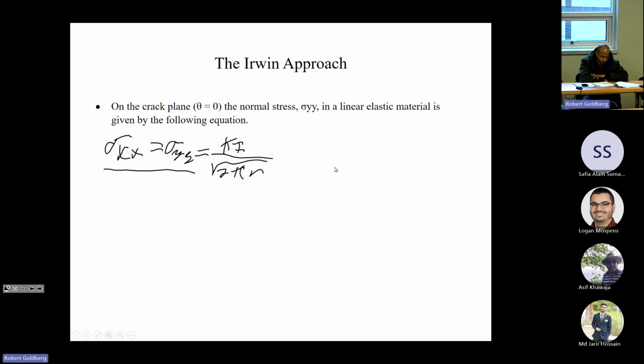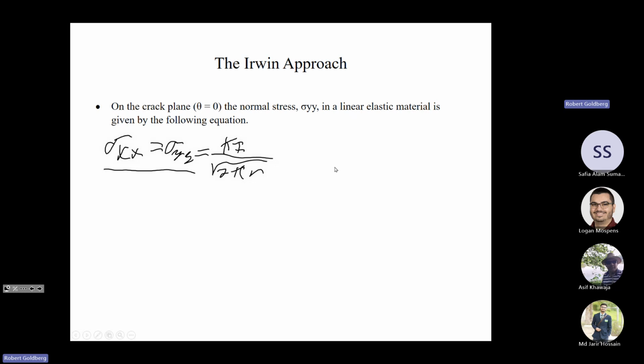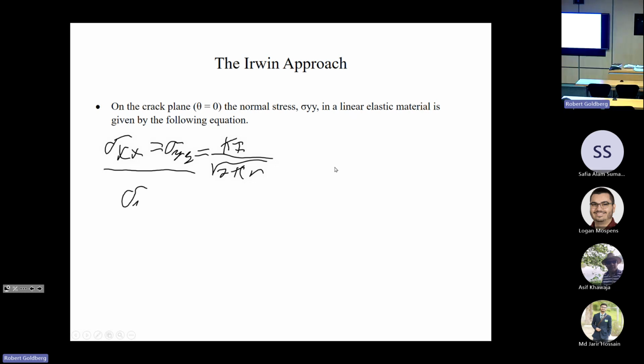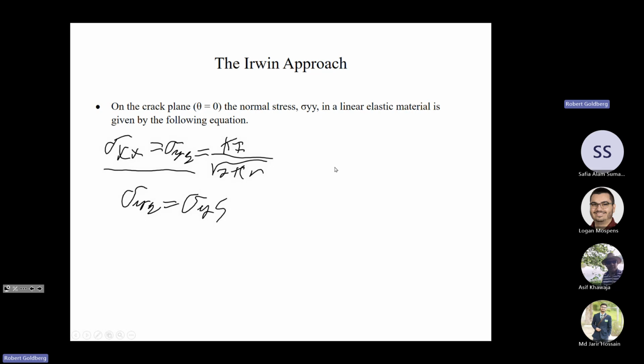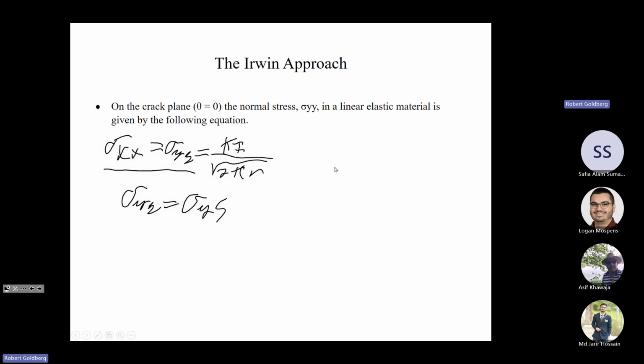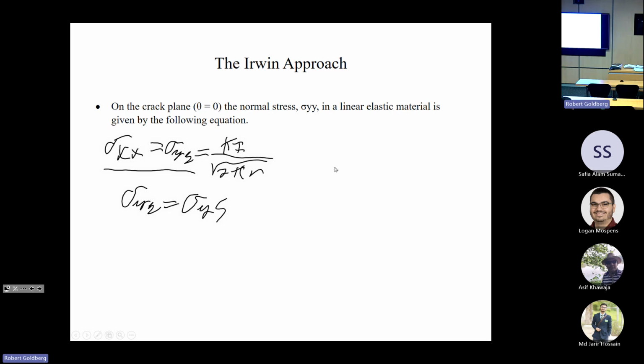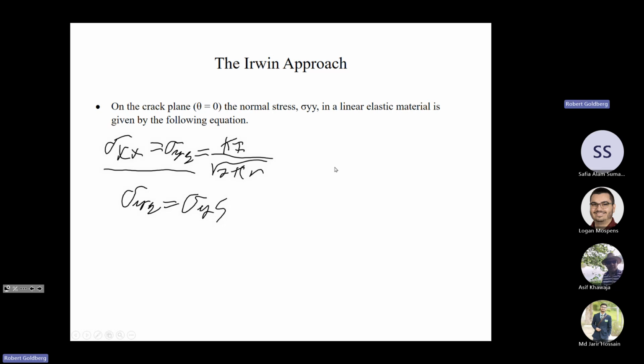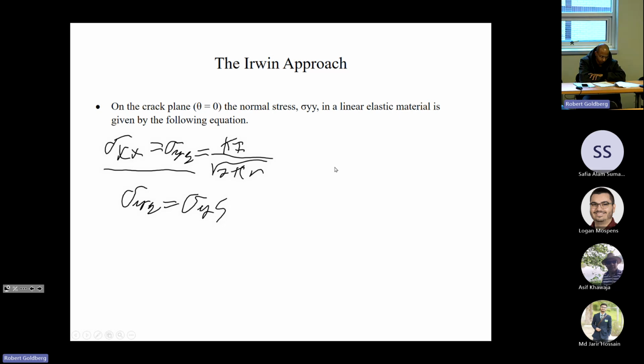We're going to look at simple plane stress conditions. So when our y direction stress equals the uniaxial yield strength of the material, we're going to say that specifies the boundary between the elastic and the plastic zone.